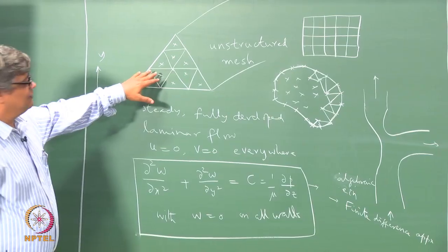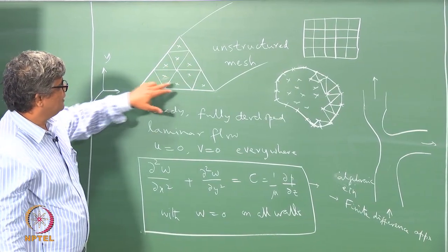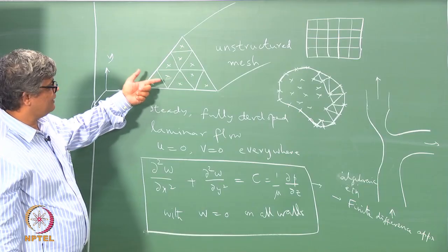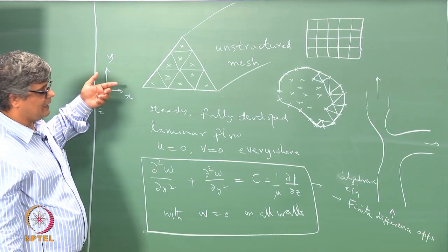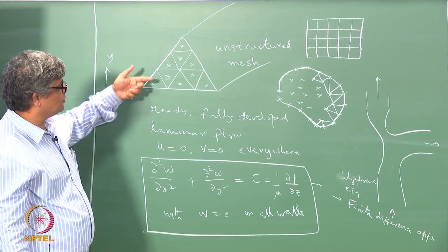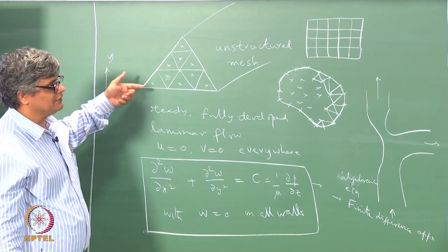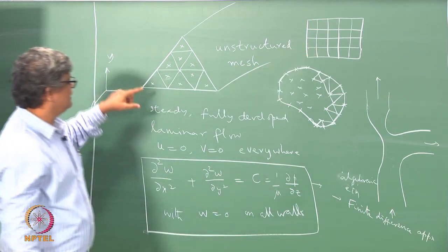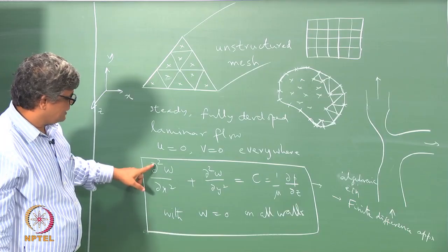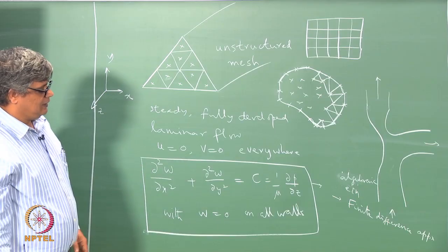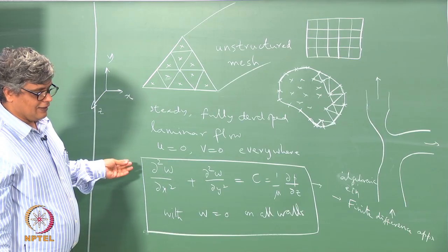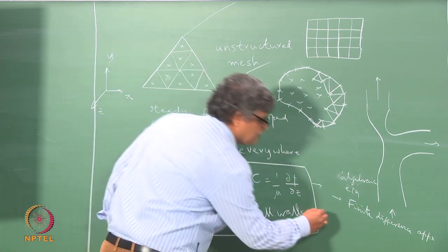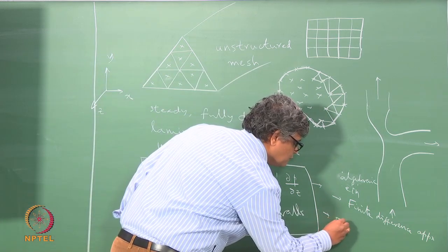And here we do not have the grid points along lines of constant values of coordinate lines. These grid points are not located at intersections of constant values of coordinate lines. And for this case, you cannot write down the previous finite difference approximations. So, what we do is that we use a different approach which is known as finite volume approach.